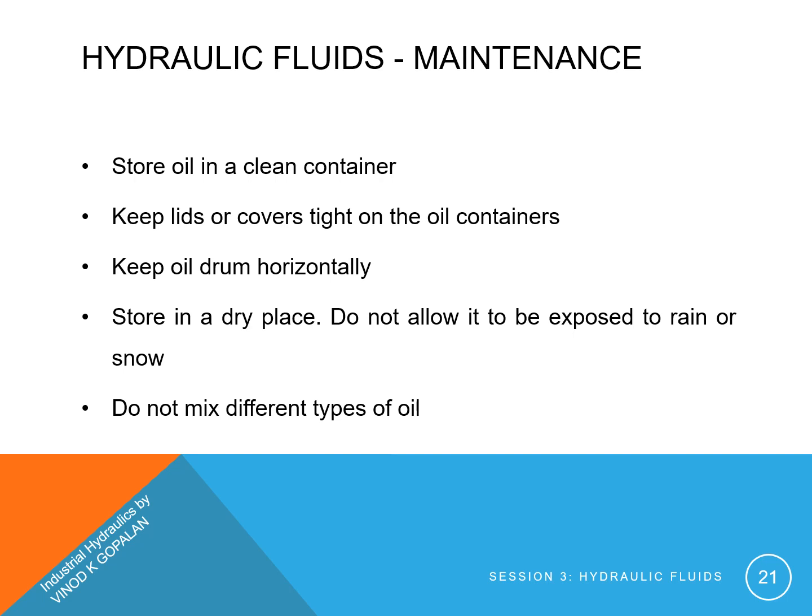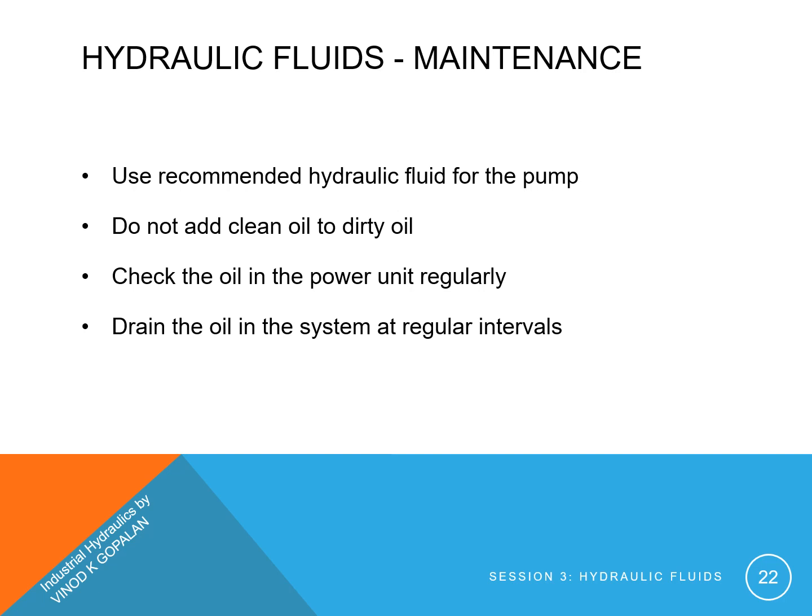Do not mix different types of oil. Use recommended hydraulic fluid for the pump. Do not add clean oil to dirty oil. Check the oil in the power unit regularly. You can send it to some laboratories for testing the properties. Next, drain the oil in the system at regular intervals.